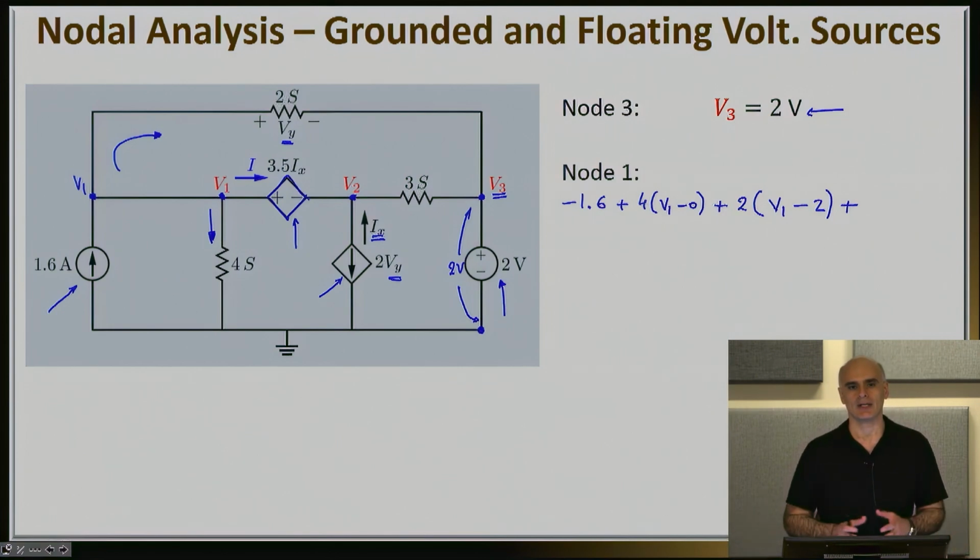Now the trouble here is that we really don't have an equation to express this current. I can't use Ohm's law for a dependent voltage source. It's not a current source where I could immediately know how much the current is. In reality, as we have discussed several times in the past, there is really no way to know how much current flows through an ideal voltage source.